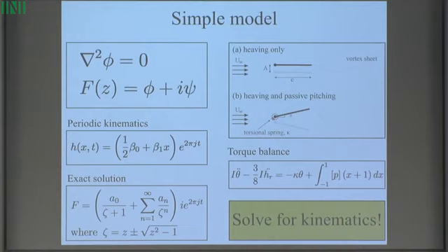But you also mentioned vortex sheet roll-up, which can be an important effect. That's not going to be captured here because I'm in the small amplitude regime. Even though I drew it wavy for illustration, in the theory, the vortex sheet is always perfectly flat. So it's not going to capture vortex sheet rollup. But having said that, this is something I would like to examine, and I'd like other people to think about it too.